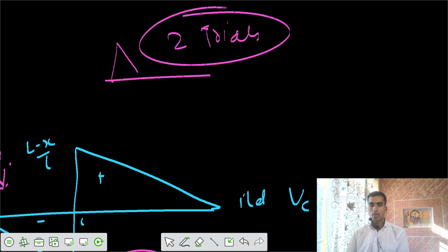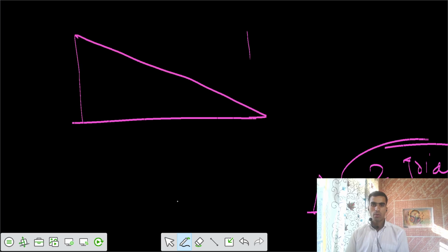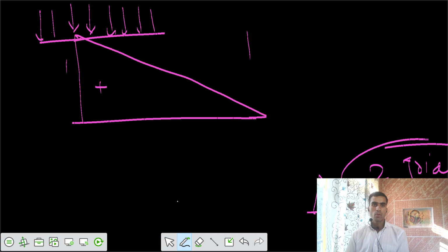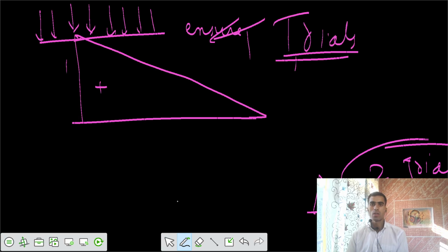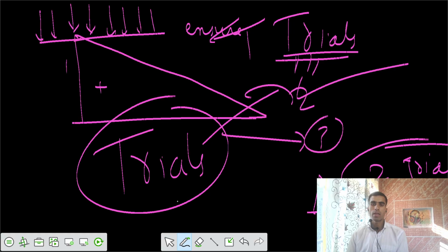We already know V absolute. For that case also, let's say maximum positive absolute shear force. Let's say the ordinate here is 1, and we can have different loads somewhere here. We can check different configurations, and a few loads we can take outside also. So we have to perform trials for this one also, for shear force. Let's try 2 to 3 trials in order to get which value would give maximum shear force.